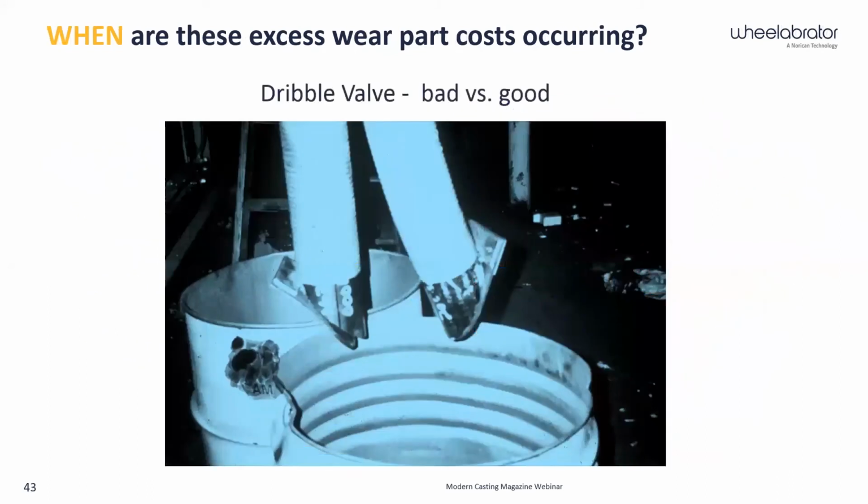Another one that a lot of people miss all the time: dribble valves. As that vacuum system is working and we're pulling from the dust collector off of the abrasive curtain, we want to be pulling what it was designed for. It's a certain CFM that was engineered, designed to pull across that abrasive curtain. This is a dribble valve that goes at the bottom of your fines tube.